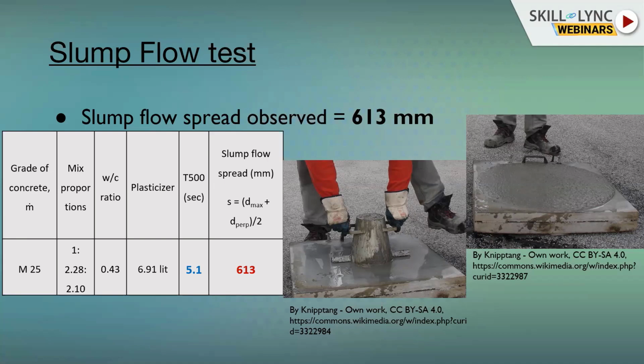Admixture may be a retarding admixture, a super hardening admixture, or an accelerating admixture. There are a lot of admixtures being used in the concrete. But nowadays the clients of large projects don't design the concrete on the site. They give the details of the design to the ready mix plant, and they order the concrete by cubic meter, whatever quantity they require, from the ready mix plant. And that concrete is self-compacting concrete, where the admixture is being used.